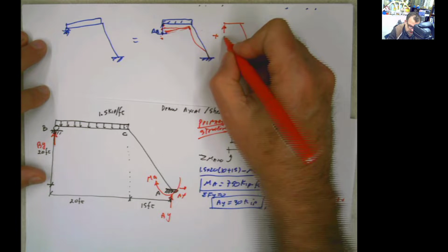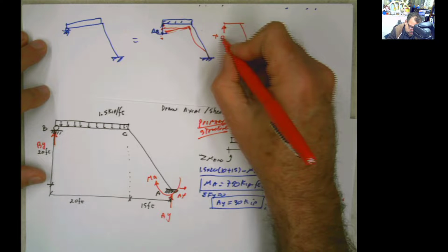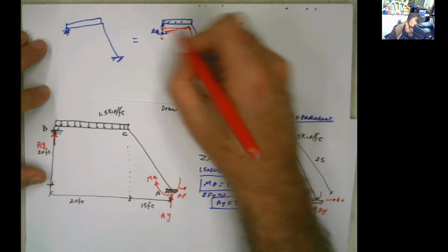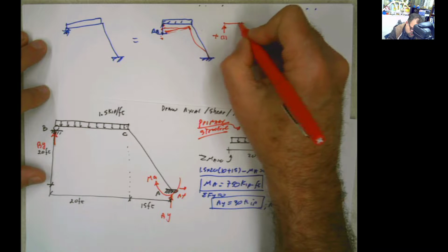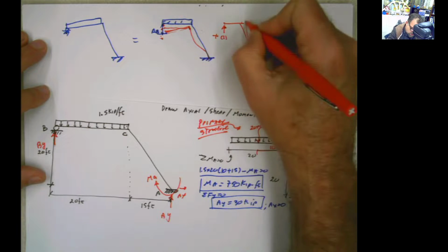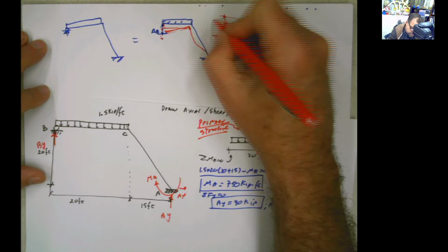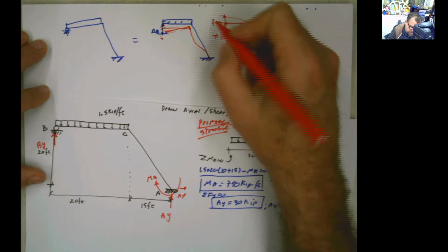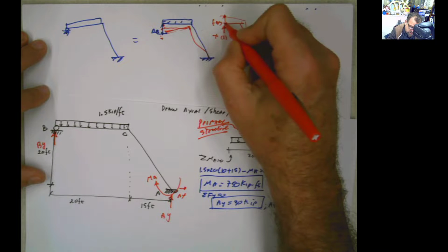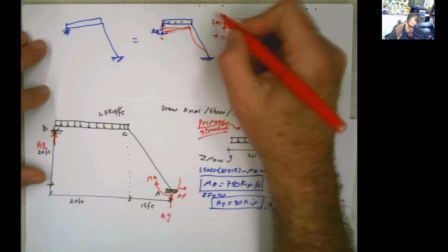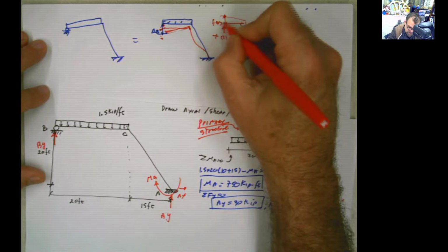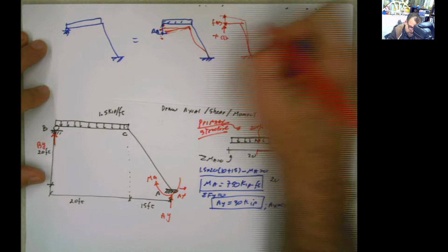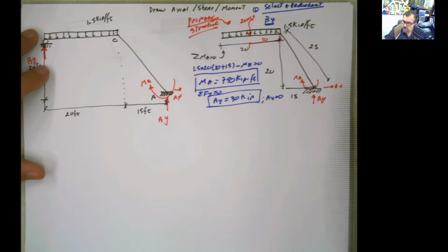And of course, I push this out with a value of 1, and then once I calculate this part, this is gonna be FBB, which is gonna be the flexibility coefficient. So this deflection here plus this FBB times By has to be equal to 0, and then we can solve. This is plain and simple virtual work method as we studied before.